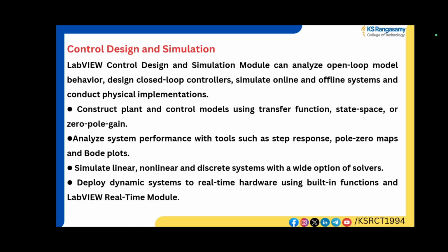Well, if we keep elaborating this, we can create models from first principles using transfer function, state space, or zero pole gain representation. With time and frequency analysis tools, we can obtain the time step response or Bode plot, or we can analyze the open or closed loop behavior of the transfer function or state space models that we have designed using built-in tools for both multi input multi output or single input single output systems. We can verify the linearity and non-linearity of the system dynamics.